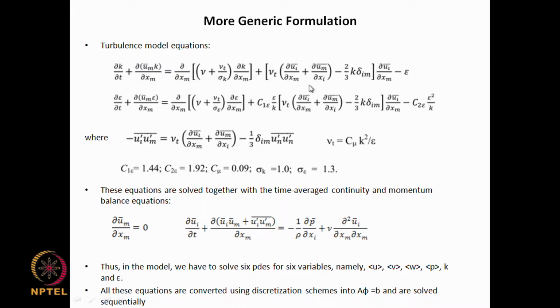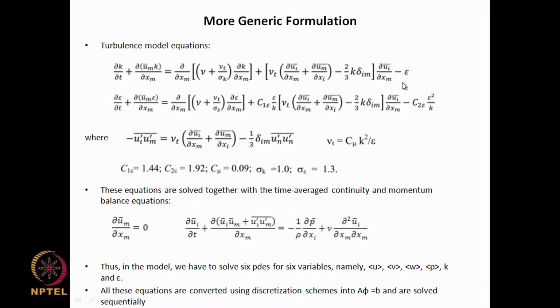this term here, and this is the Reynolds stress term, and one can show that for typical flows this is a net positive thing. So that means that if all the other terms are not there, dou k by dou t will increase because of this. So this is known as the production of k, and this involves mean velocity gradients. We know that turbulence is produced primarily by the energy containing eddies, produced by strong mean velocity gradients, and so this is a production term of k, and this is the epsilon which we have seen, the definition of